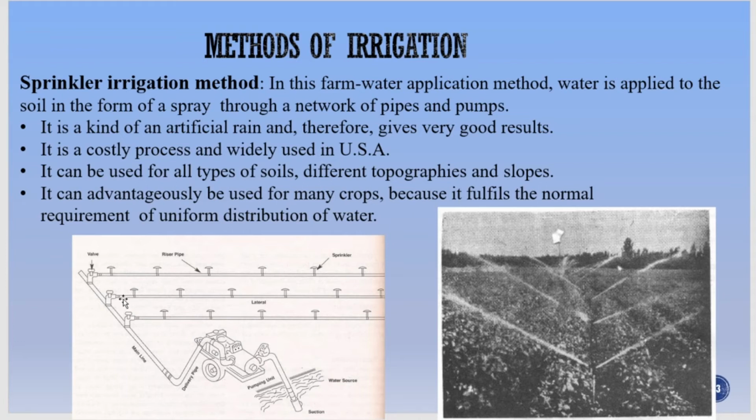So what the farmer or the engineer does is try to understand how much pressure is required at every valve. He designs the pump station and the valves in such a way that he maintains the pressure at all these different points. He measures the pressure required at all these points. Based on that, the nozzle opening is done, and all these nozzles will discharge the same amount of water, though the pressure may vary at each nozzle, the discharge should remain the same. Like that, the nozzles are designed.